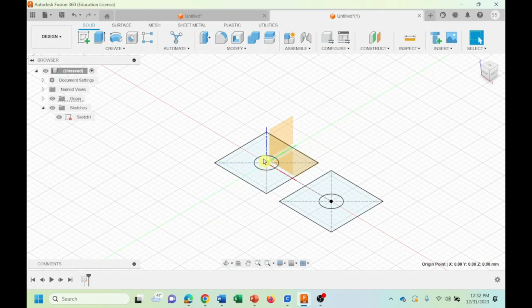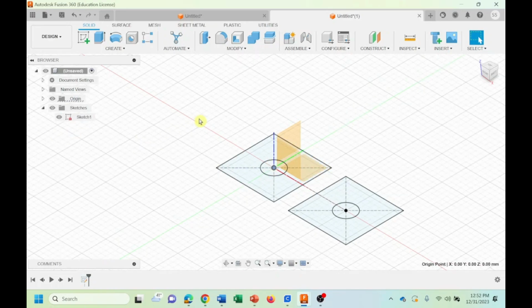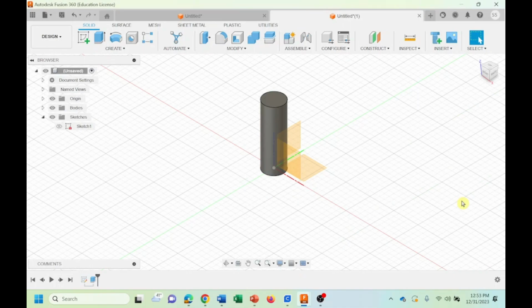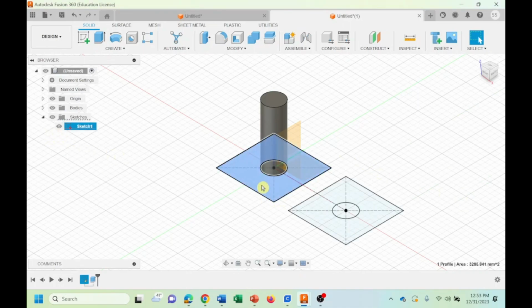I come here, the first one, extrude this one. Yeah, I select that. Now I say extrude. Here it is the same thing for the distance of the extrusion. We have the circle height, right? If I click on C, it brings me circle height. I select the circle height, and it goes there. I say OK.